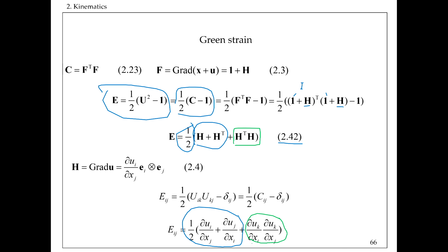So we have this ability to capture the nonlinear term in strain. All right, that will be all for illustrating the strain. The bottom line is that it is up to us how to define it. But if we choose to define this measure of strain, we need to do it smartly. According to our problem, if we know that there are large deformations and geometrical nonlinearities, of course, let's take into account the nonlinear terms.